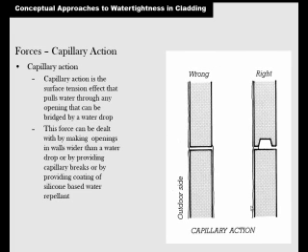Capillary action is where the tension effect that pulls the water through an opening can be bridged by a water drop. So this is the wrong way because that can just fill with water and it can go down. This is the right way because that's bigger than the water drop, so the water drop stops there. Although I think this wouldn't be the ultimate solution because it could still squeeze on over that way, but it's better than this side.